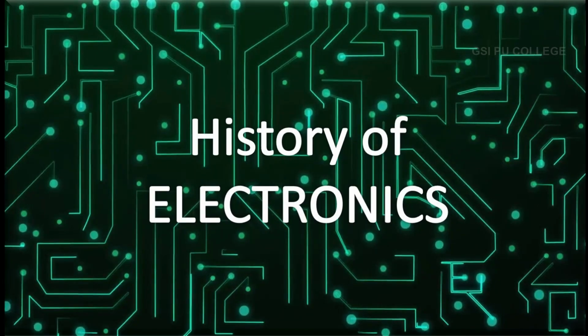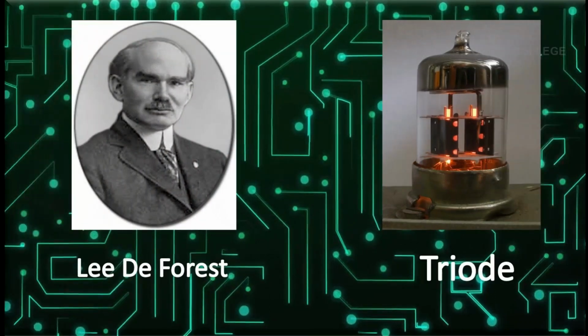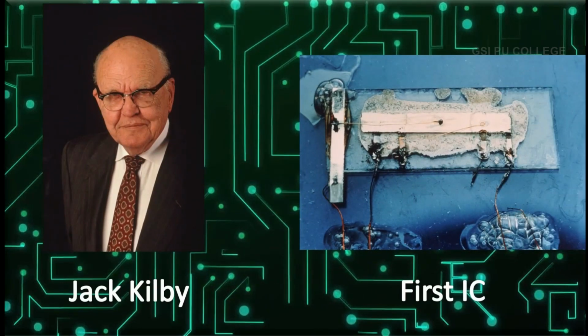Now let us see the history of electronics. The diode vacuum tube was the first electronic component, invented by J.A. Fleming, that is Sir John Ambrose Fleming. Later, Lee De Forest developed a triode, a 3-element vacuum tube capable of voltage amplification. Triode consists of 3 electrodes, cathode element, anode plate, and control grid, used as an amplifier, as an oscillator, and in electric circuits. In 1947, Bell Laboratories developed the first transistor based on the research of Shockley, Bardeen, and Brattain. In 1959, Jack Kilby of Texas Instruments developed the first integrated circuit, which is usually known as IC.